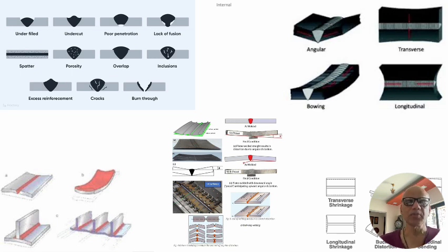Cracks, obviously, because of improper shrinkage, improper parameters, improper welding consumables, you will land up in metallurgical defects. The cracks, when the material is cooling down, it doesn't cool uniformly, and there are certain voids which create something like porosity, but porosity is a small defect, whereas here it is a large defect which actually creates a planar defect.